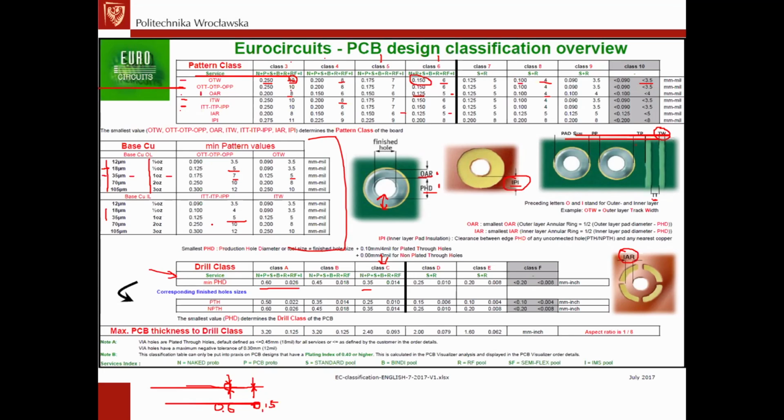These are actually the most important parameters that you must know before the design process begins. So TW is really the major parameter, but the copper layer cannot be neglected. The standard is 35 microns, but as you can see, there is a close connection between the copper thickness and the allowable or possible track width.